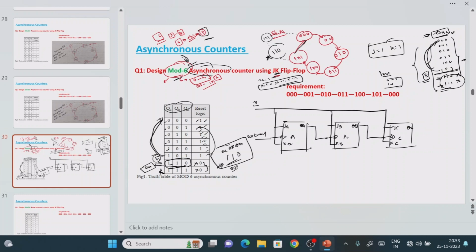How we can find out the answer in the easiest way is, this is one logic you can remember. The first flip-flop value is QA, the second flip-flop value is QB, the third flip-flop value is QC, right? So always LSB to MSB like that only we need to take, as the logic we explained in the previous class. Don't try to take something like QA, QB, QC, right?